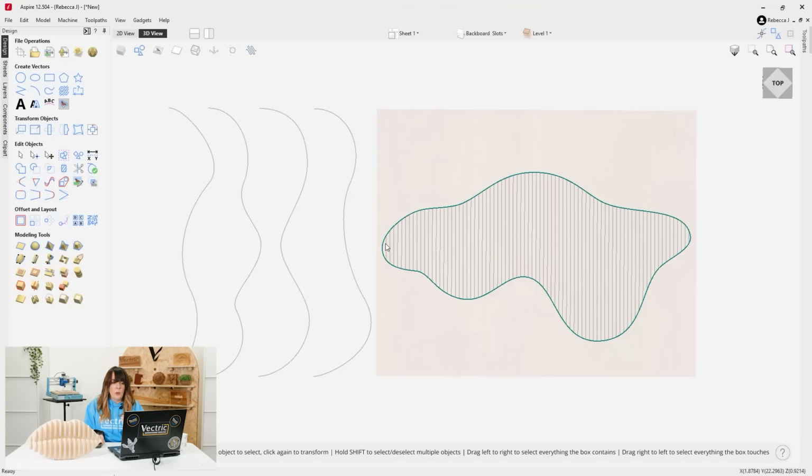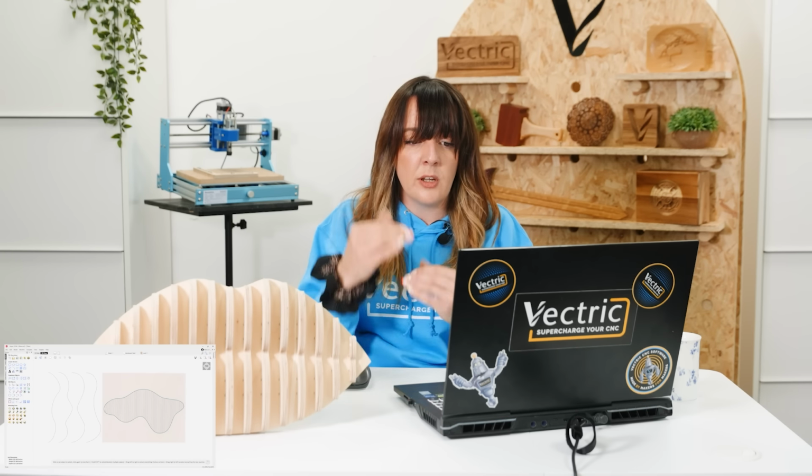Now, I know when we get to the edges over here, they're actually going to be quite small, because obviously where the curvature of the actual backboard is, we're probably not going to get a 2-inch slot in there. It'll cut through. So we can tweak that as we go. So I'm going to go around 2-inch slots. They're going to be the same as the material thickness. And the idea is on the backboard, we're going to cut all the way through, okay?